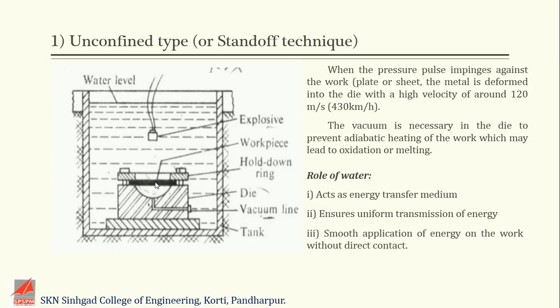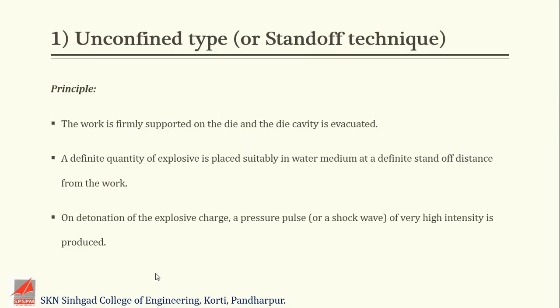If stand-off distance is more, then proper or 100% deformation of the workpiece will not take place, and if stand-off distance is very less, then more deformation of the workpiece takes place, and it may lead to cracking of the workpiece, or it may damage the dies also. That's why stand-off distance is a very important part to maintain in case of this unconfined type explosive forming process.